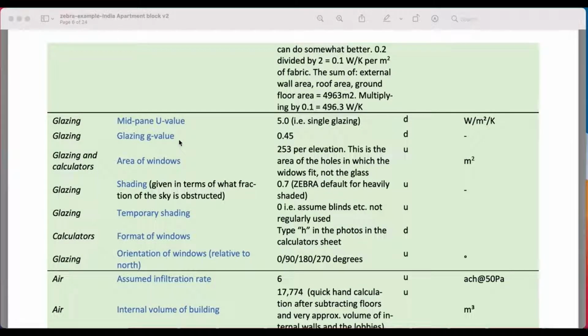One of the reasons it's complex, or maybe the main reason it's complex, is the fact that if you don't get glazing right within a thermal model, you've really got a problem. For example, it's very common, it depends where you are in the world, but on a summer's day, there's often about 1 kilowatt of heat in the form of light hitting a square meter of horizontal surface. So on your roof or through a glazed window on the roof, for example, for 1 meter square of ground, you've got a kilowatt of energy.